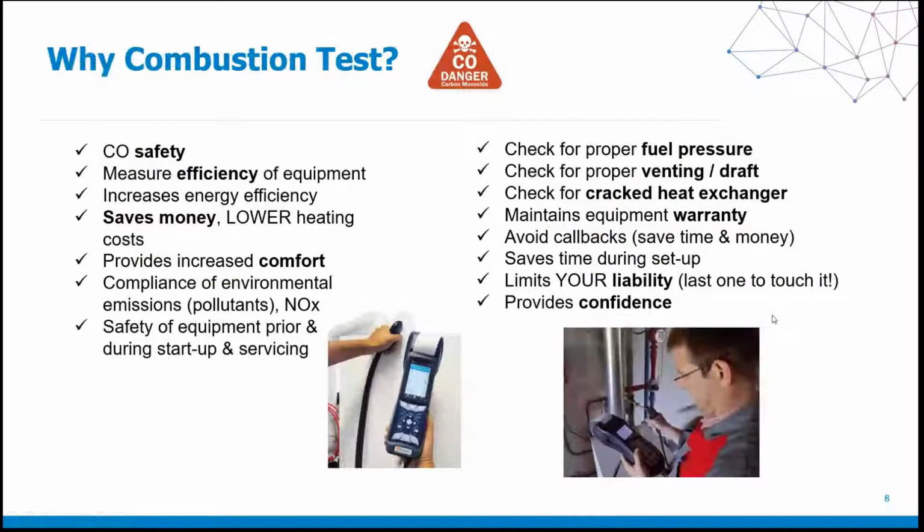Why should we combustion test? Well, first and foremost, it comes down to safety, and that being CO safety. Everything else follows suit after that. So once we have the safety factor established, and we're making sure that not only our own personal health is assured, but the health and well-being of those living or occupying the space is assured, then we need to look at the diagnostics. We need to measure for efficiency of the piece of equipment.